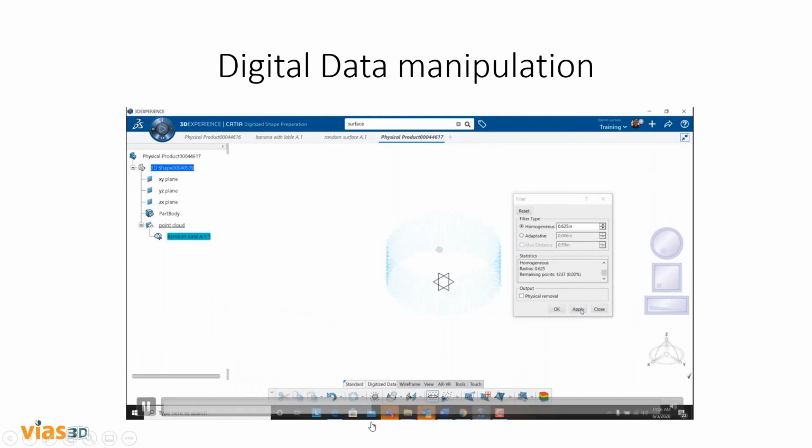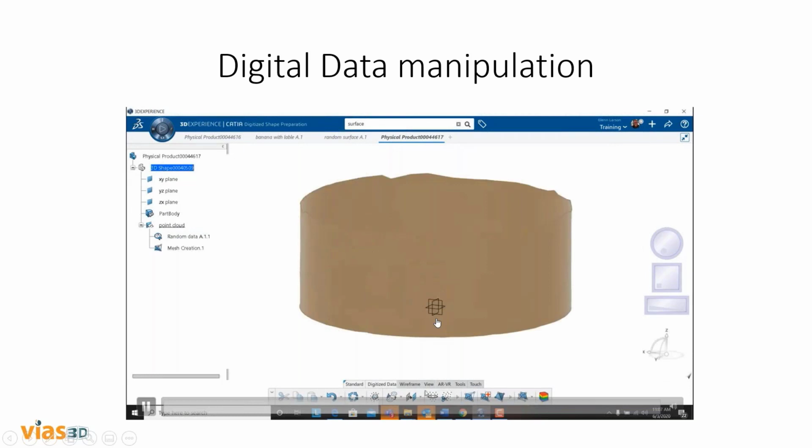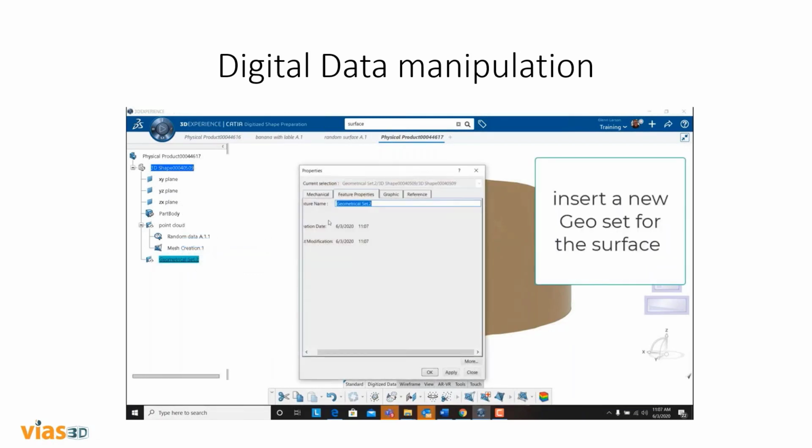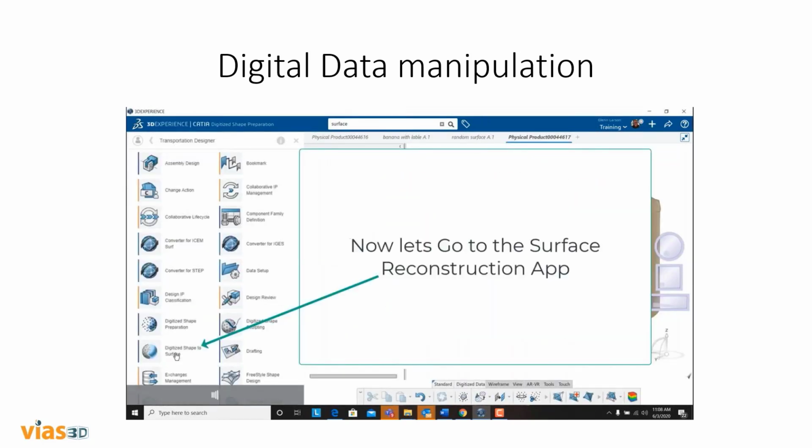Out to creating a mesh. So you put a mesh on that points, and you can see the mesh really shows the deformation of this tank. So in this case, I'm going to create a model from it. So I'm going to trim the extra added surfaces because they always scan above the surfaces. So that's why it gets a little funny at the top.